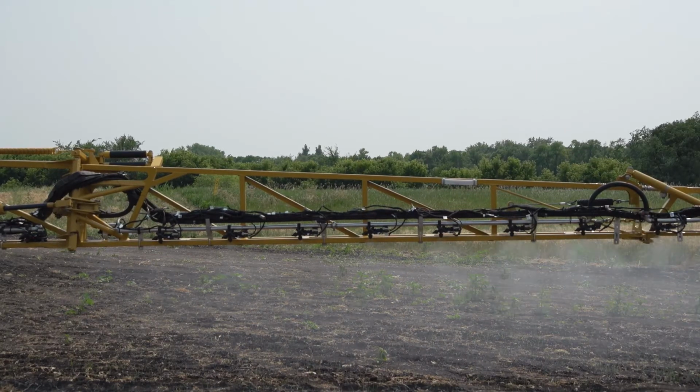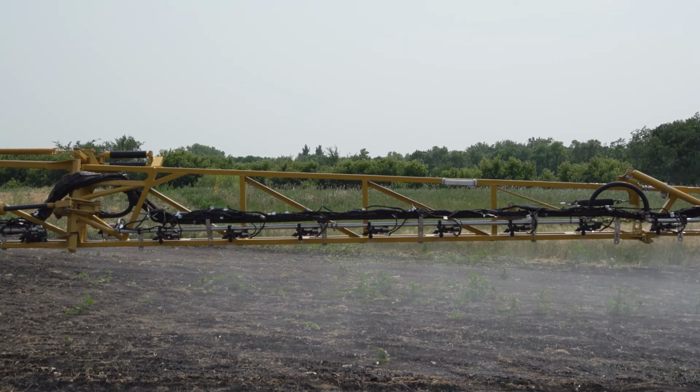Okay, and now going on to the second example. Here we're still in the same section of the boom, but we've introduced a nozzle that has a problem. I want to just take a minute for you to scan all of the nozzles that are on at this time and see if you can pick it out of the crowd. There's one nozzle that has limited flow. It's not a full blockage, it's not fully off, but it has some kind of a flow problem. Did you catch it yet? Okay, so it's actually this one.